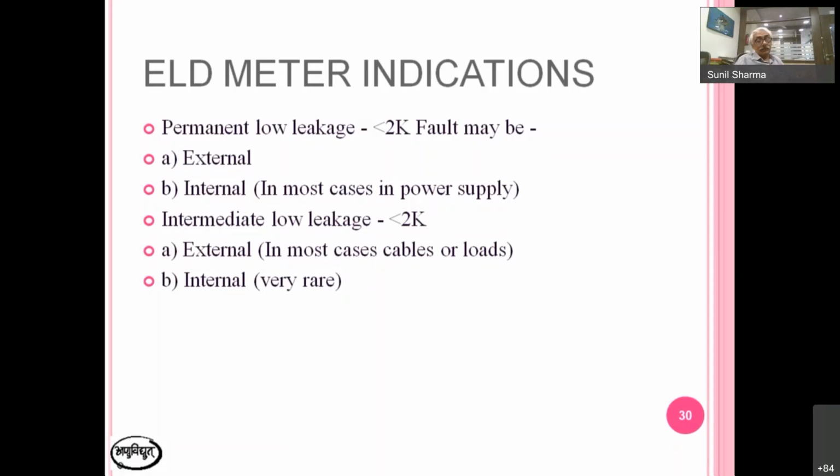One lead connects to earth, the green one, and the other connects to the body. In our insulation tester there are 2 leads, so both leads connect to the body. On the different side, you have to find whether its insulation is okay or not okay, because when you remove the electrolyte from the surface with cotton, a very fine film remains on the surface and it is very conductive.